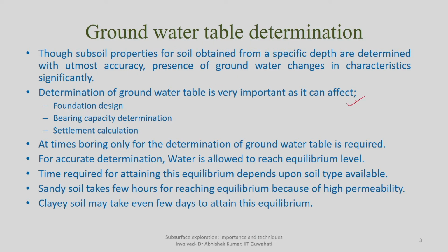So, it depends upon whether the particular depth from which the soil sample was collected falls below the groundwater table or above it. Accordingly, your foundation behavior will change. That is what it means: though we determine the laboratory-based soil characteristics properly, if we do not assess the groundwater table depth properly, it will again lead to erroneous judgment in foundation design, settlement, bearing capacity and all that. So, the determination of groundwater table is very important as it can affect several things.